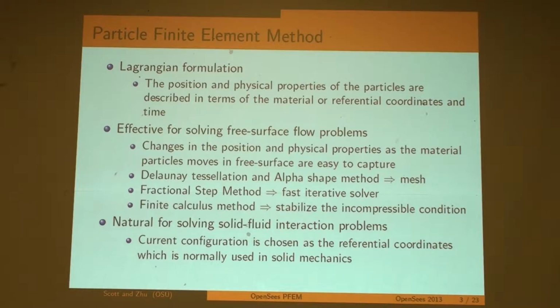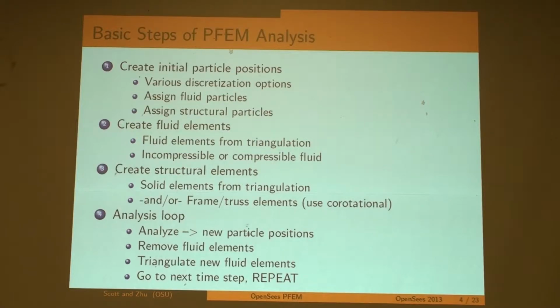Okay. So this PFEM has been developed over the last 10 years or so, mostly out of Spain. We've decided this could be a practical way to do FSI with OpenSees because it fits in with the Lagrangian formulation. Okay, so it's kind of natural for solving fluid structure interaction problems.